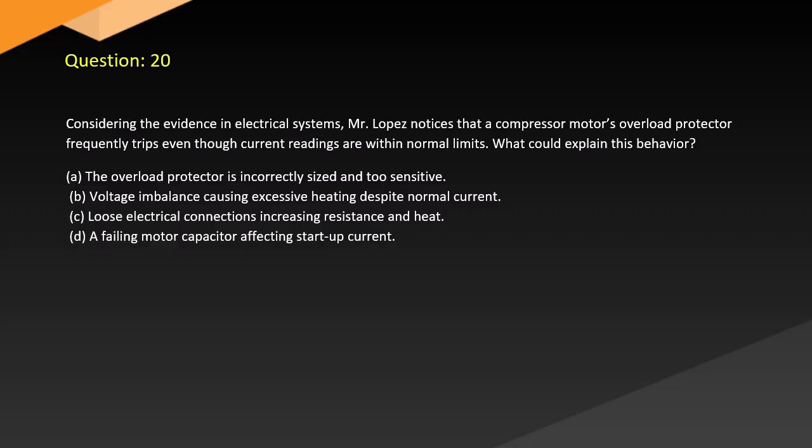A. The overload protector is incorrectly sized and too sensitive. B. Voltage imbalance causing excessive heating despite normal current. C. Loose electrical connections increasing resistance and heat. D. Failing motor capacitor affecting startup current.